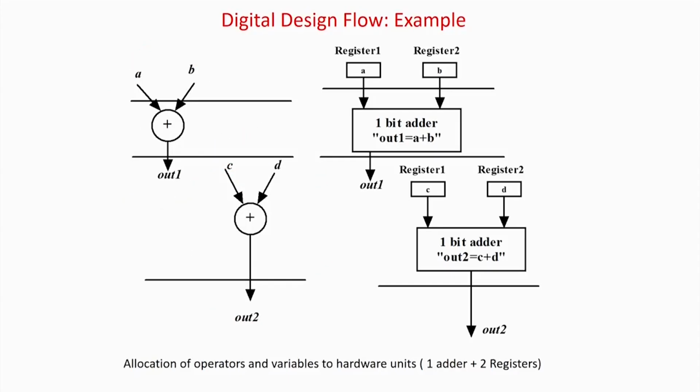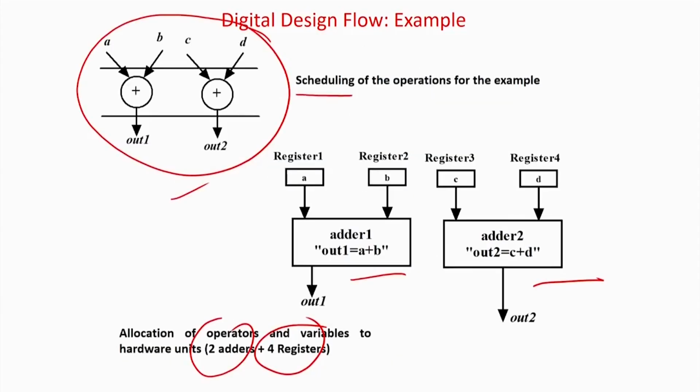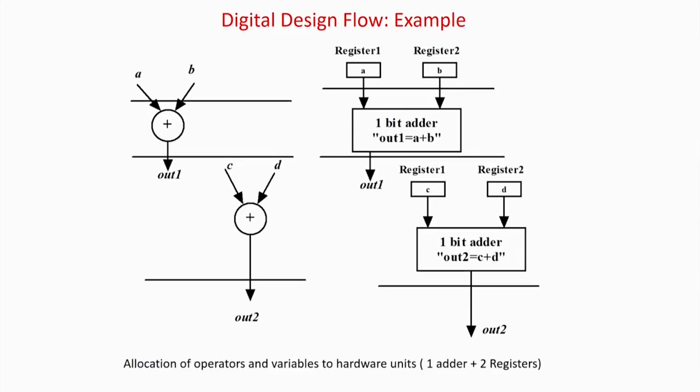So this is called scheduling. Based on your requirements and dependencies, you have to get an optimal schedule. There are lots of textbooks with algorithms which, given the requirements of speed, power, time, etc., can generate good quality schedules for you. A lot of optimization can be done depending on the resources available and your timing requirements. Like this example will take more adders but give you the solution faster, while the other has low area overhead but the time of generation is slow.